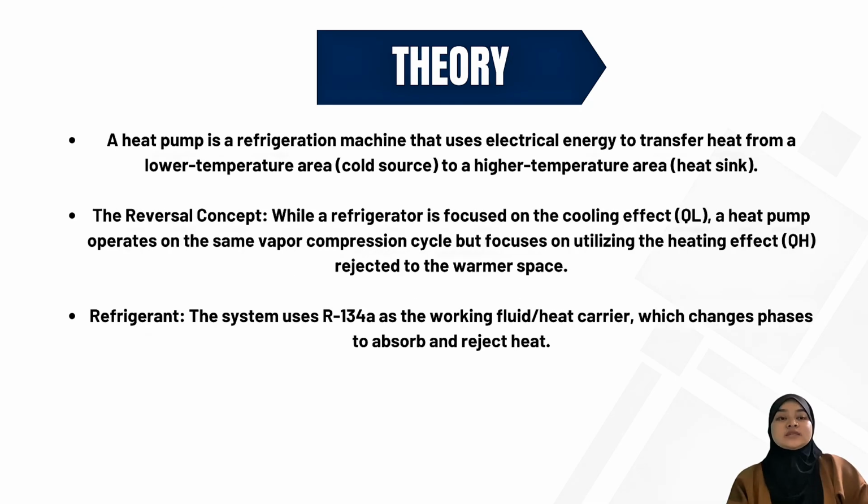A heat pump is a refrigeration machine that uses electrical energy to transfer heat from a lower temperature area, the cold source, to a higher temperature area, the heat sink. The reversal concept: while a refrigerator is focused on the cooling effect QL, a heat pump operates on the same vapor compression cycle but focuses on utilizing the heating effect QH rejected to the warmer space. Refrigerant: the system uses R134a as the working fluid or heat carrier, which changes phases to absorb and reject heat.